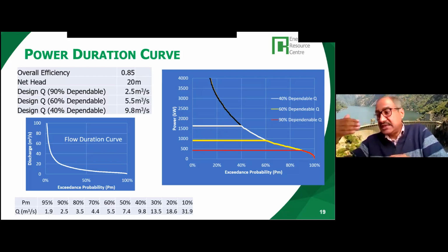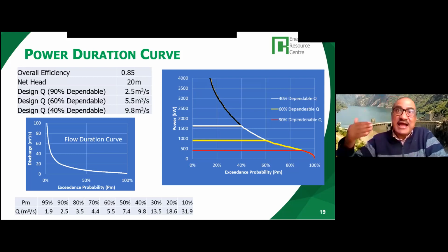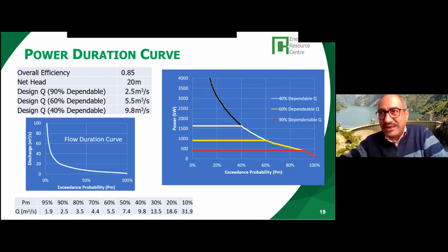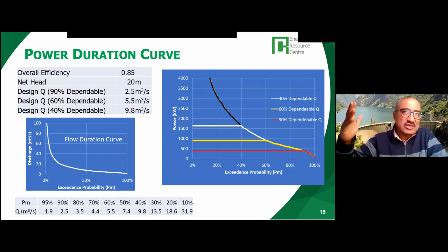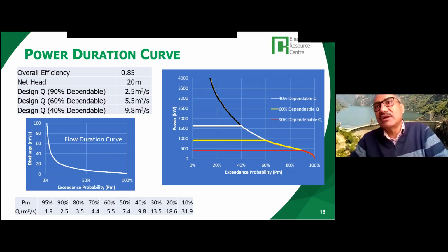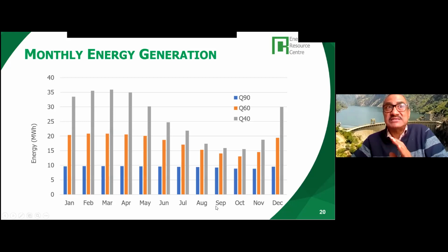For example, the Majao hydropower project is designed for, I think, 4.5 cubic meter per second, which is available 12 months in a year, always. So it always generates 585 something kilowatt. But you could design Majao for a higher installed capacity, though the reliability, or the exceedance probability, of that power will be different. So this is a very important part of the hydropower design capacity optimization problem.